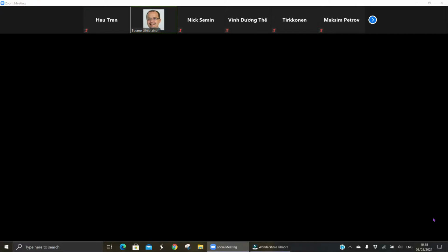In here you can see some examples, practical applications of friction joints. So here in this left picture there's, I don't know actually what is the device in the hub, some flange or probably just connecting the shafts. Seems fairly big in diameter compared to the brick sizes in the wall behind. So obviously it seems that the hub in the center is somewhat heated because there's a brownish color in it, and the shaft halves have been cooled down, and we can see it from the frost.